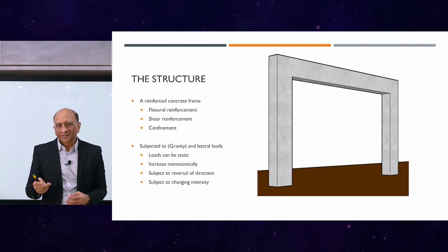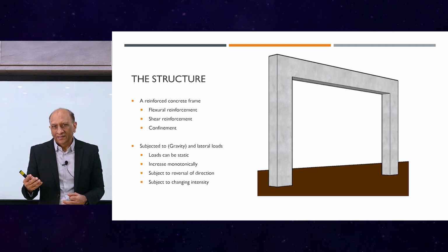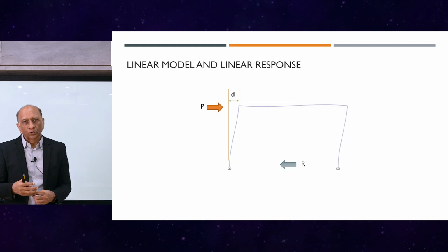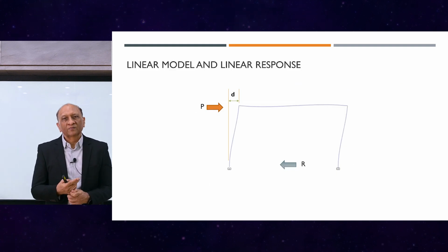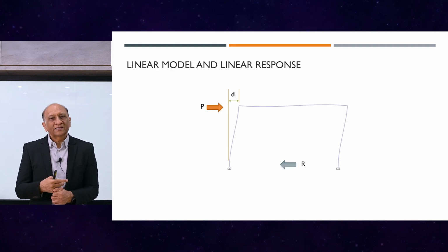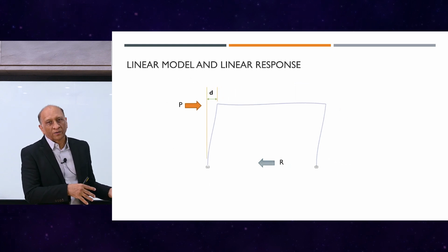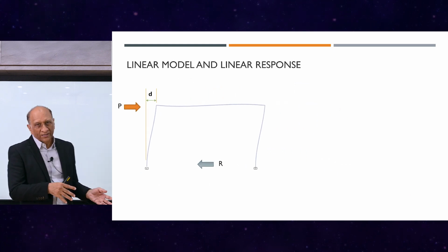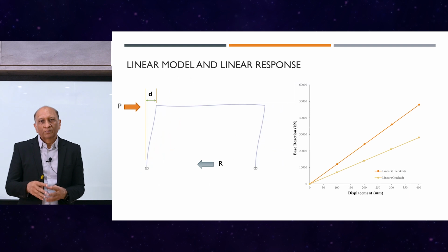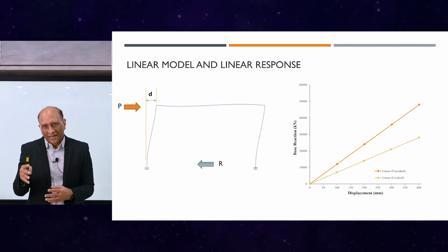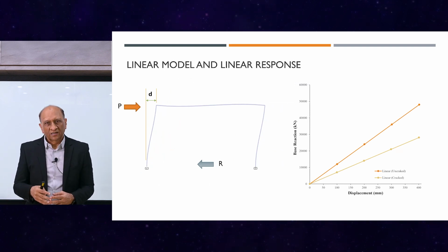And once you do that, then you can see that we get the nonlinear capacity now, not the assumed one. So here we have 2 nonlinear capacities. One is without P delta, and the second one is with P delta. So you can see that nonlinearity is not just coming from cross-section or rotation or the hinge rotation, but also coming from the P delta effects. And so when you include that, the capacity drops significantly further.